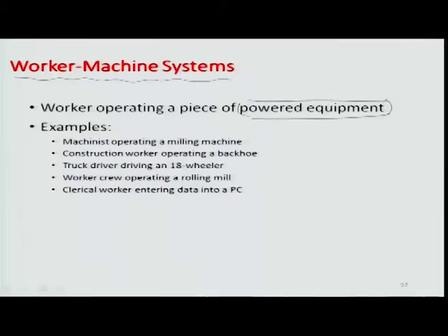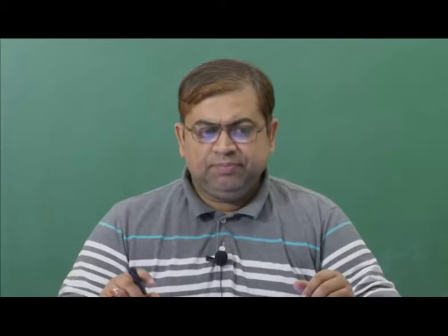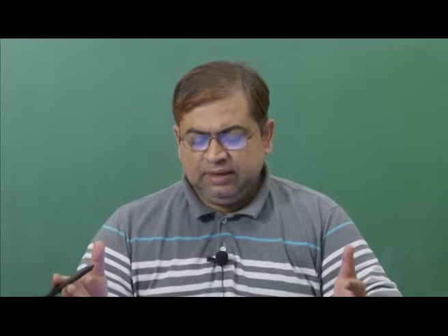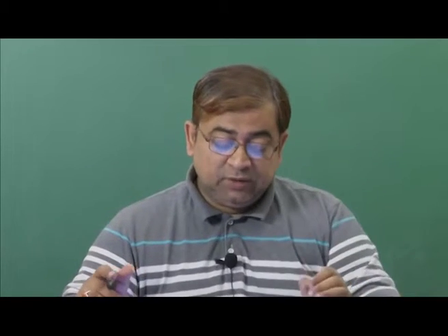Some examples could be a machinist operating a milling machine. Once the milling machine has been set up, the indexing has been done, and the arbor as well as the tooling and the workpiece are mounted, it is left, after the switch on button, to the motor of the milling machine to provide the power and drive the various stages in sequence, so that there can be gear cutting or some other operation which is intended to happen.